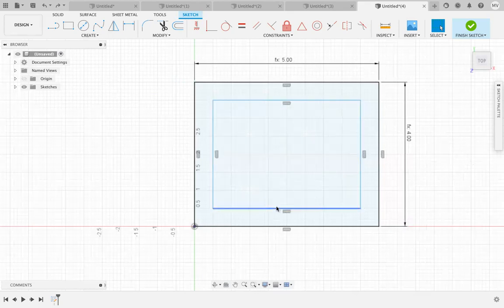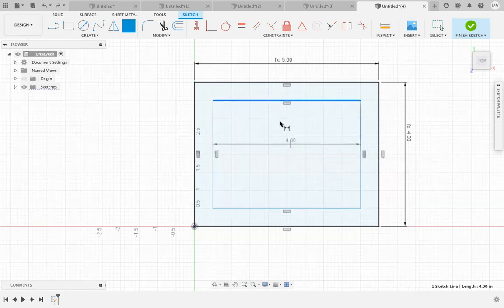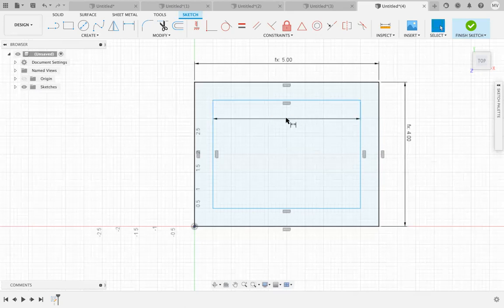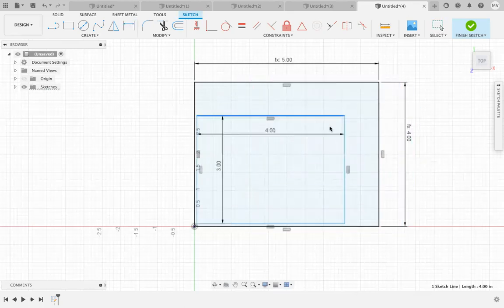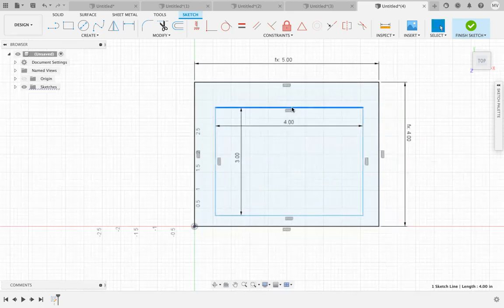You might think, all right, well, I need to change the lengths and lock them to be a specific length. So if I click on this side and I press D, 4, click there, hit enter on 4. Okay, cool. Now that can't be changed in size. If I do the same thing on this side, 3, hit enter. Now this has to be 4 and has to be 3. Fine, but when I click this, I don't change the size anymore, but it's not locked in space.